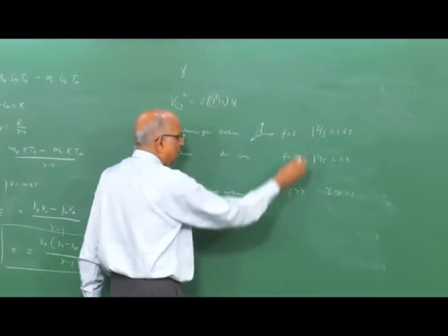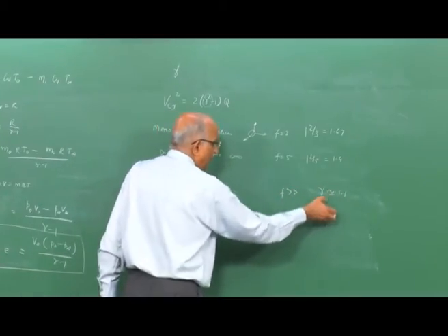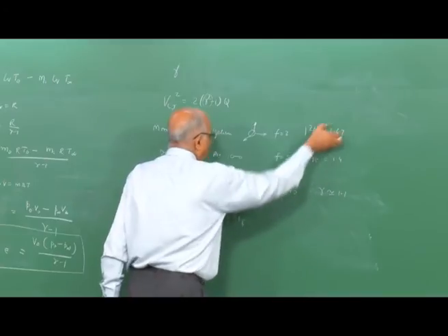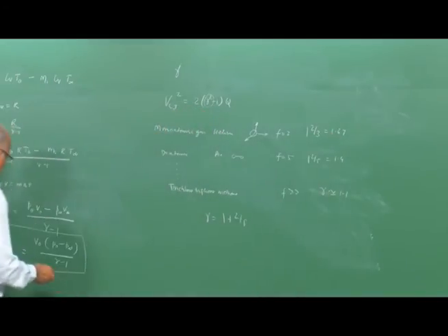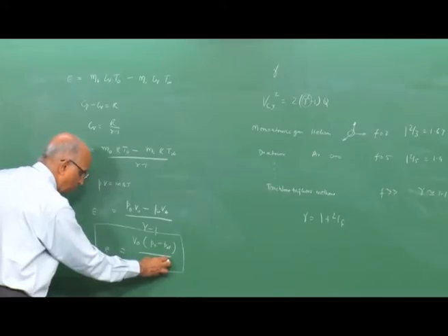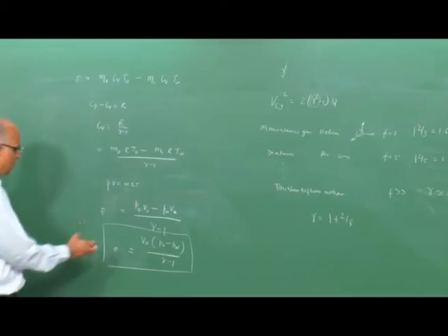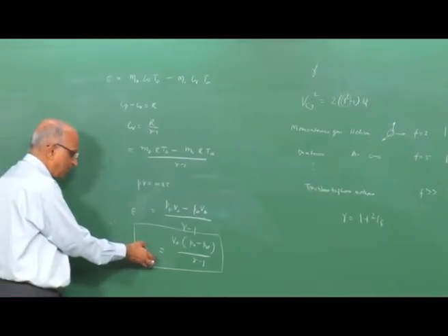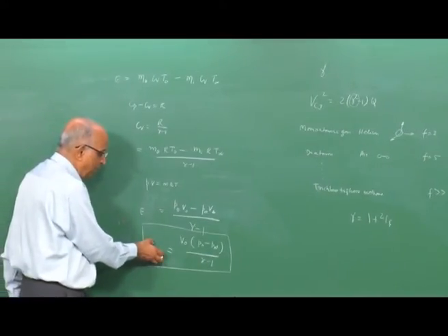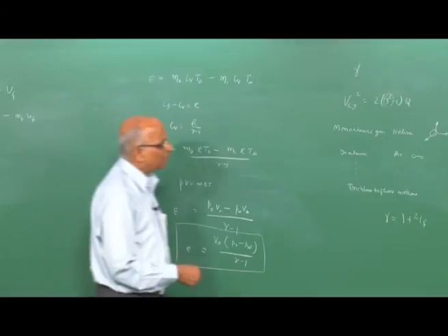And therefore, for a heated gas which is very hot, maybe the gamma will be very low. And when we talk of a low value of gamma, in my denominator I have gamma minus 1, therefore the denominator becomes a small number, and therefore the energy release goes up. Therefore, let's do a small problem to find out the sensitivity of the energy release in the explosion of a pressure vessel with respect to the value of gamma. Let's do this problem.